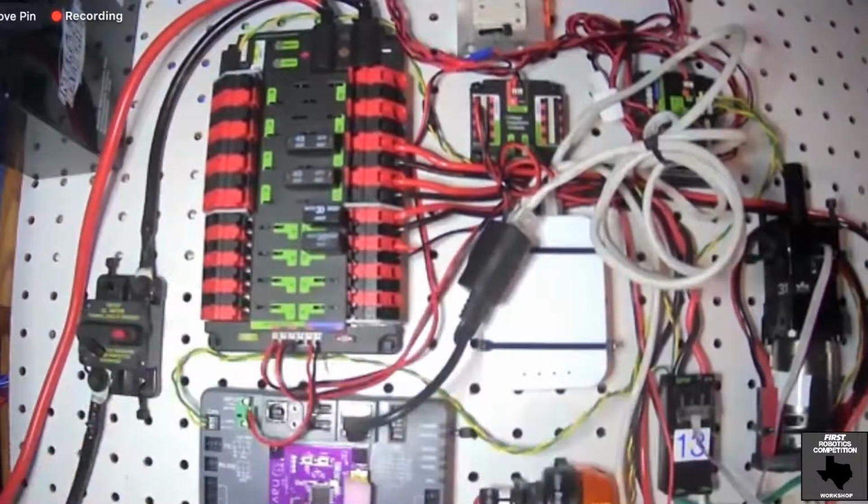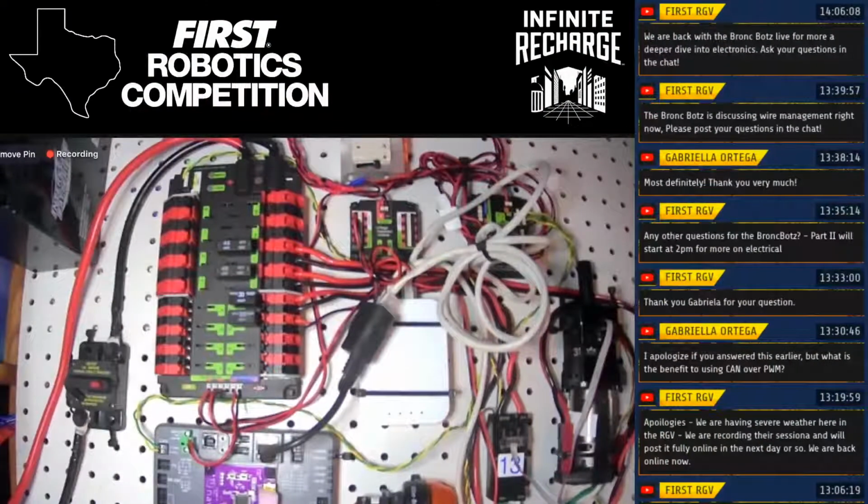So the reason we don't use fuses on the main spots on the PDP is the same reason we don't use fuses in your house. In your house, what they call a circuit box or a fuse box is actually what's called breakers. A breaker will disconnect the circuit just like a fuse, but it won't break itself. It'll reset after a certain amount of time, or you can manually reset it. So it will only shut down for a period of time based on the current drawn.